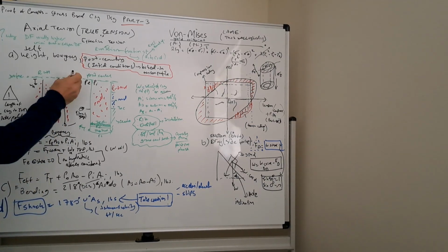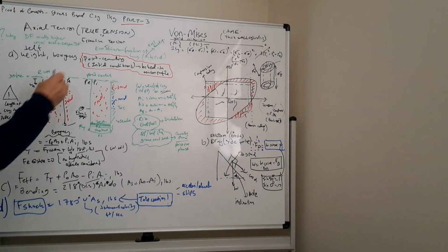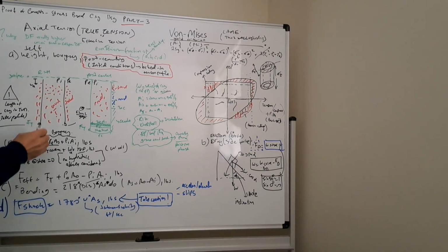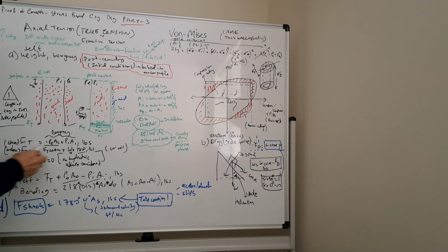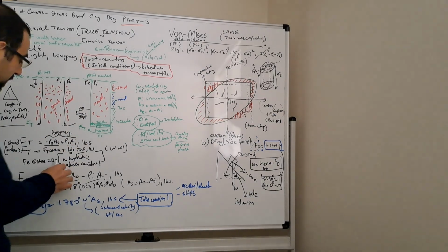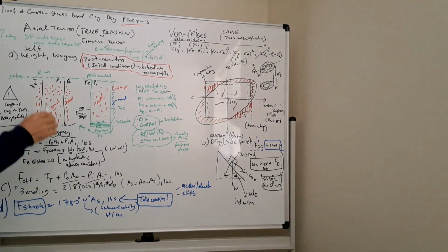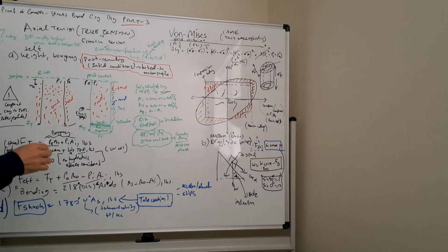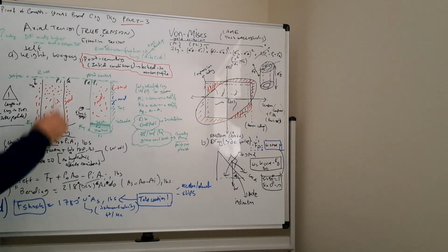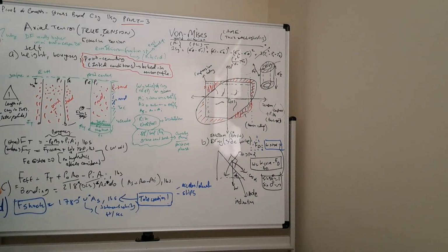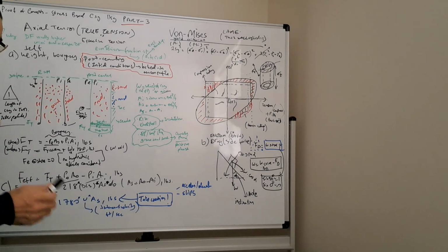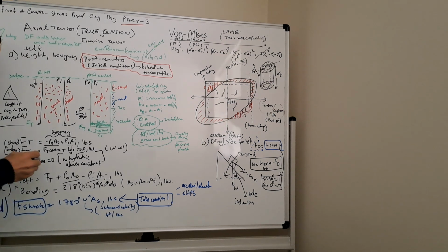And if I want to calculate, let's say, the true tension at the surface, what do I need to do? So I calculated here the true tension at the shoe. I need to add the weight of the casing in the air multiplied by the TVD of the casing length. All right, same as the hydrostatic assumption. So they use the same assumptions in the TVD.